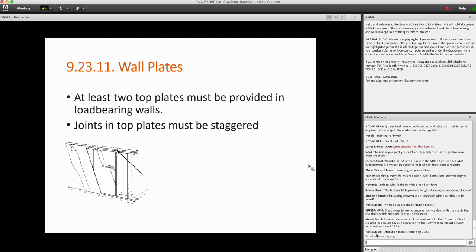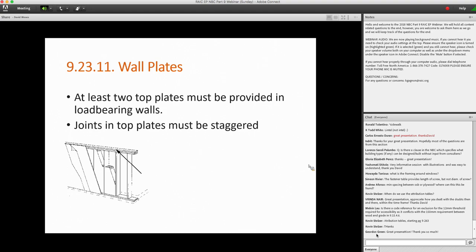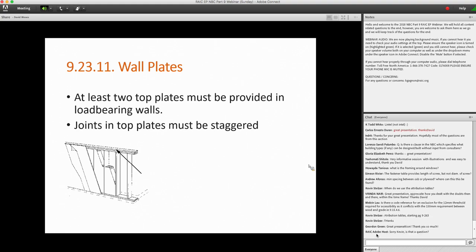Well, the requirement for the 150 millimeters to raise the foundations above the grade is for the typical foundation requirement, but at entrances and doorways, that would have to be waived so that people can enter the building. But as I understand it, the reason for raising the foundation at those locations is to protect the structure above. And since this would just be a doorway for accessibility, I can't see that that requirement would need to be kept.